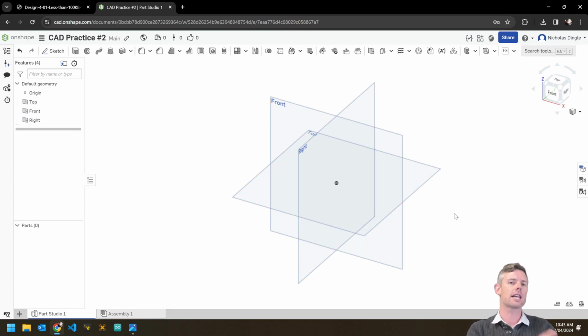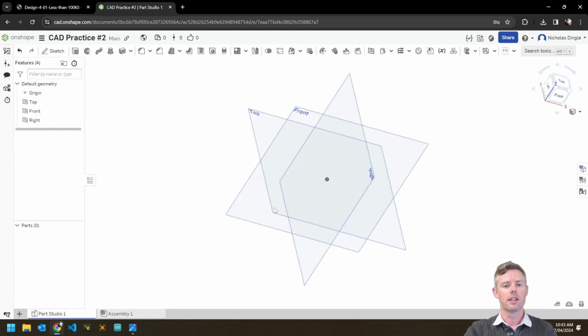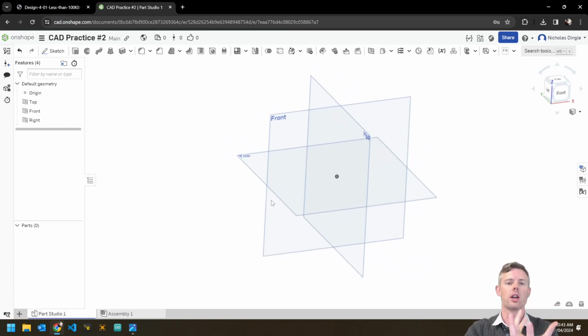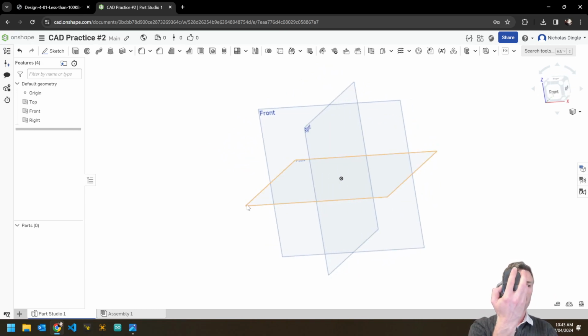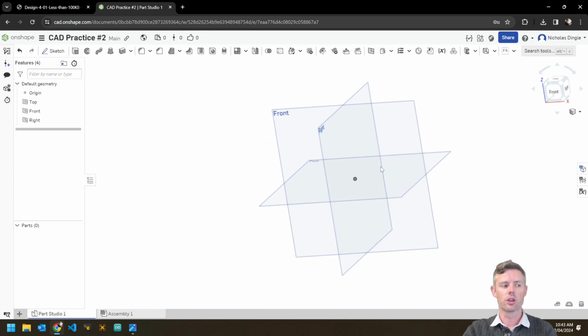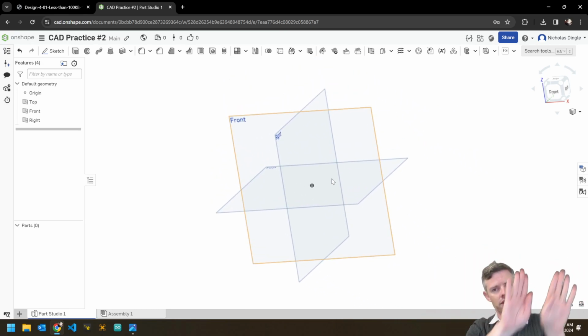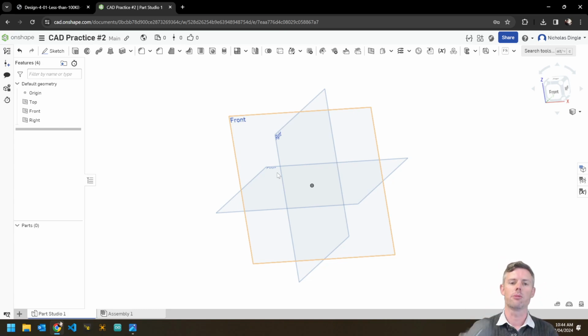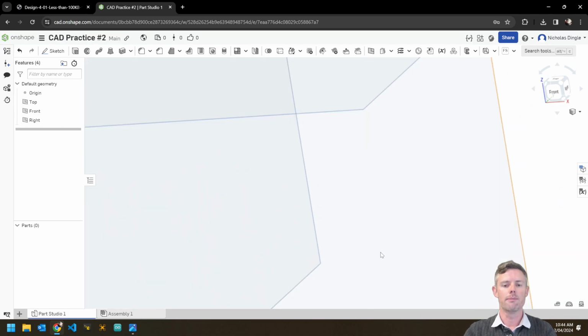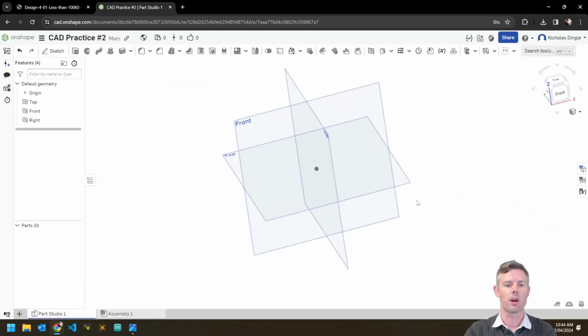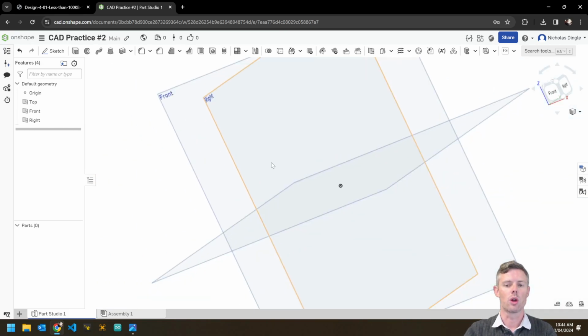Now our workspace, this is where, as we build our model, we do our drawing. It's where it's going to appear. This is where we make our things 3D, chop out holes, round off edges, all that kind of stuff. You can also navigate this. I would recommend make sure you've got a 3-button mouse, something with a scroll wheel in the middle. Because if I right click anywhere, I can drag this to rotate our 3D object around. If I click the mouse wheel or middle click and hold it, then I can do what's called a pan. So that's moving up and down, left and right. If I scroll up and down on my scroll wheel, it'll zoom in on my mouse cursor, wherever it may be. So right click to rotate, middle click to pan, scroll to zoom.